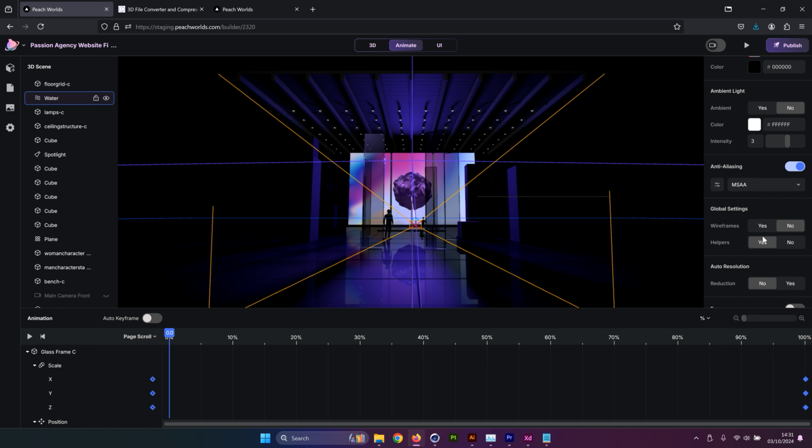Another thing that I wanted to mention, guys, is anti-aliasing settings. And what basically those settings do is removing sort of jagged edges on the 3D models and objects in your scene. There are two settings, SMAA and MSAA. We're going to make a separate tutorial about these, but we recommend to use MSAA. That will bring a very nice look of your scene and remove all of those jagged edges on the 3D objects. All right, so let's preview.